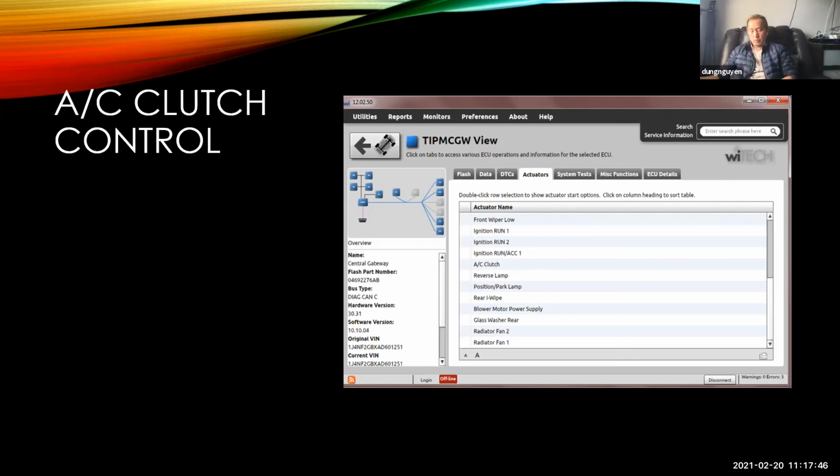So before you go in, you cannot find it. So you have to go look on a wiring diagram and see where the network is going to the module. Exactly. And we're really not wasting any time, because if we find out that it's wired to a module that won't give us control, then we know maybe our scan tool is a piece of junk or the manufacturer never gave it to us. And same with sensors. If I'm going to diagnose a sensor with an incorrect value, I'm going to pull the wiring schematic up anyway. So we're not wasting any time. We're just getting good information instead of just jumping underneath the hood and tearing at a sensor.